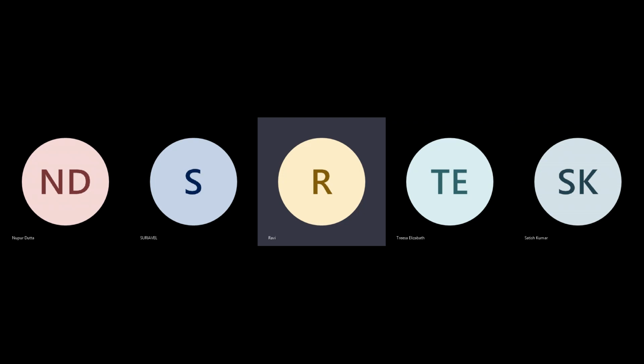As the temperature reduces, there is a diffusion problem, and then your delay is also increasing even at the lower temperature because the diffusion gets dominated. So you need to understand that there's a resistor effect and there's a PN junction recombination there. These two are converged. This is true in higher technology or lower technology, both the cases.